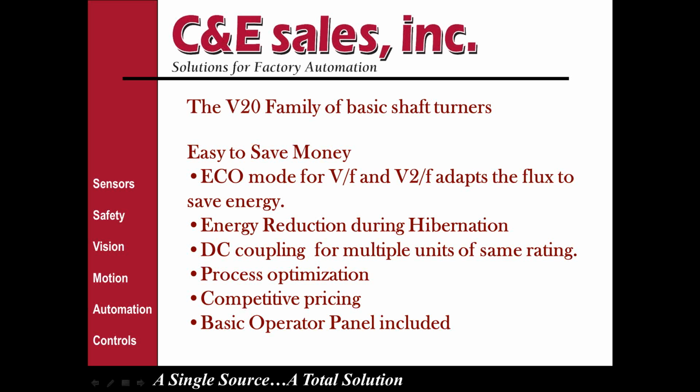If you have applications with multiple drives, and those drives vary in the timing of the load, you can do a DC coupling where the energy generated by braking in one drive can be fed into the other drive. This is really nice if you're doing test stands where you're running a motor on one end and then using a second motor for braking for testing. The generation can be coupled back in, which can greatly reduce the amount of energy you're using.